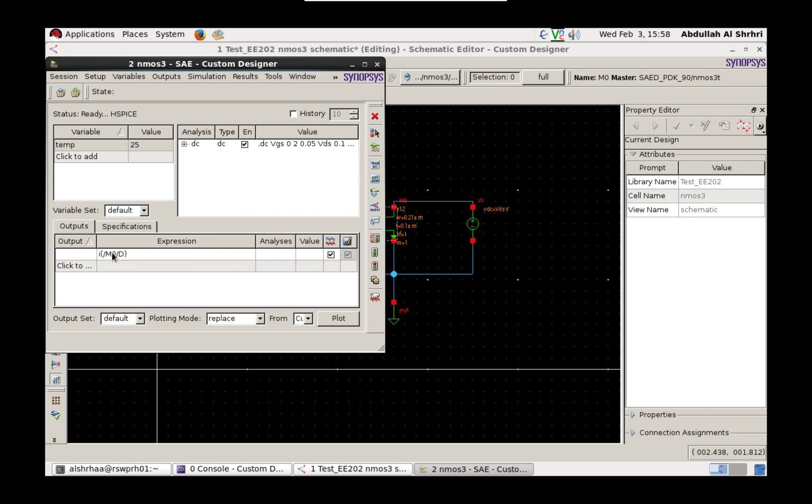Now we have this current in the drain. You can name it as well. Let's say ID, or leave it the same, and put the variable, copy from the design. It gives you the variable in the design. Let's give it 0 value. That means this avoids floating. Now inshallah it's gonna work. Let's go here, list and run.